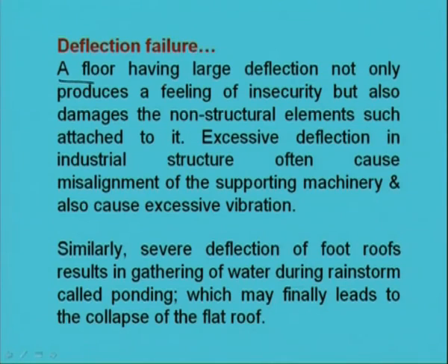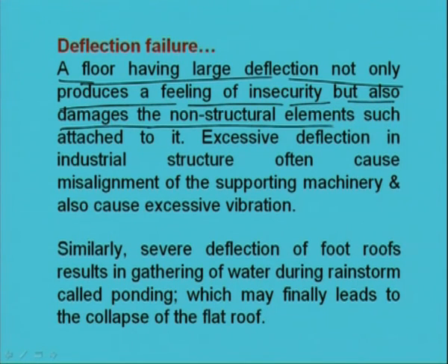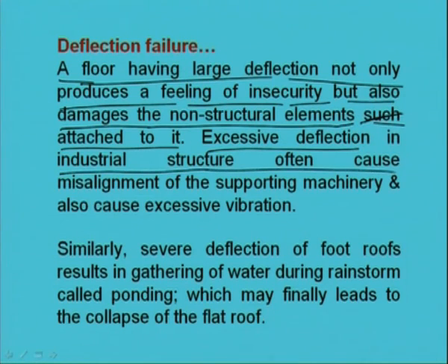A floor having large deflection not only produces a feeling of insecurity, but also damages non-structural elements attached to it, such as plaster and other architectural finishes. Excessive deflection in industrial structures often causes misalignment of the supporting machinery and also excessive vibration. So, these are the possible problems due to excessive deflection.